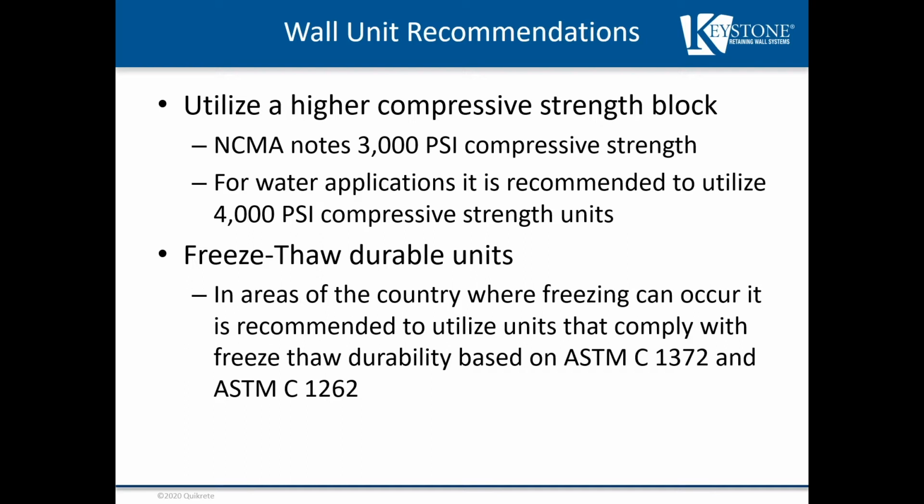Freeze-thaw durable units are recommended in those areas where rapid freeze-thaw can occur, especially day in and day out. So where the units are going to be exposed to rapid freezing and thawing, freezing overnight, thawing during the day, those types of things, we want to make sure that we have a unit that is able to withstand those effects as well. It is recommended that our units comply with ASTM C1372 and ASTM C1262.